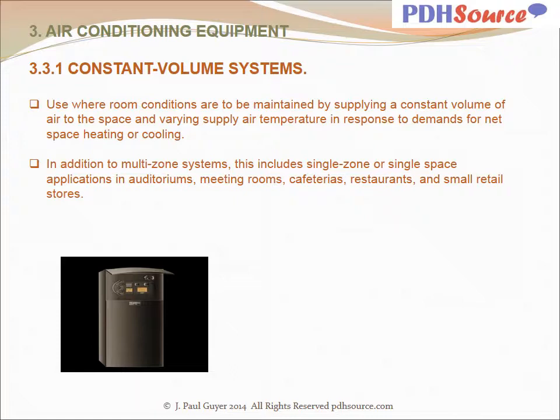Multi-zone systems provide individual temperature control of a number of small zones, maximum of 10 zones, from a central air handler. For normal comfort cooling applications, place heating and cooling coils in the air handler. For applications where humidity control is critical, place coils in series so that the air is conditioned by the cooling coil prior to passing to the hot deck.